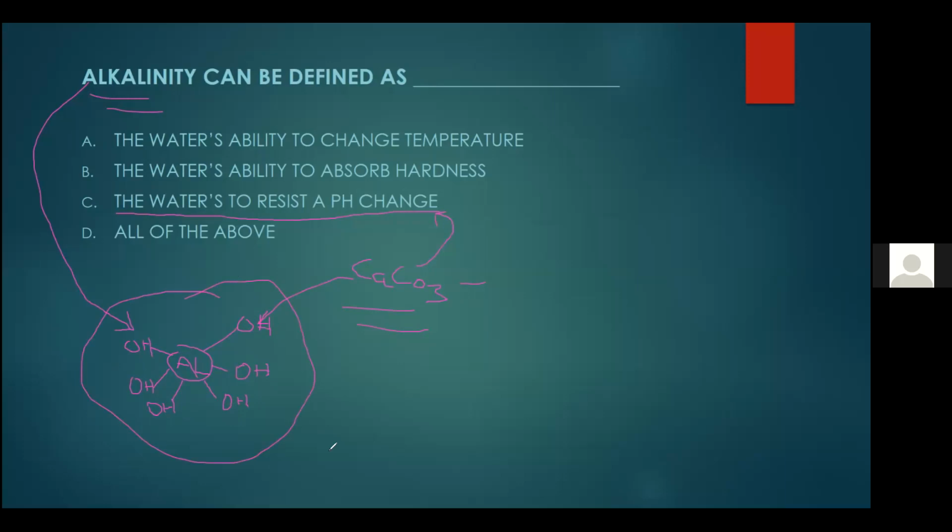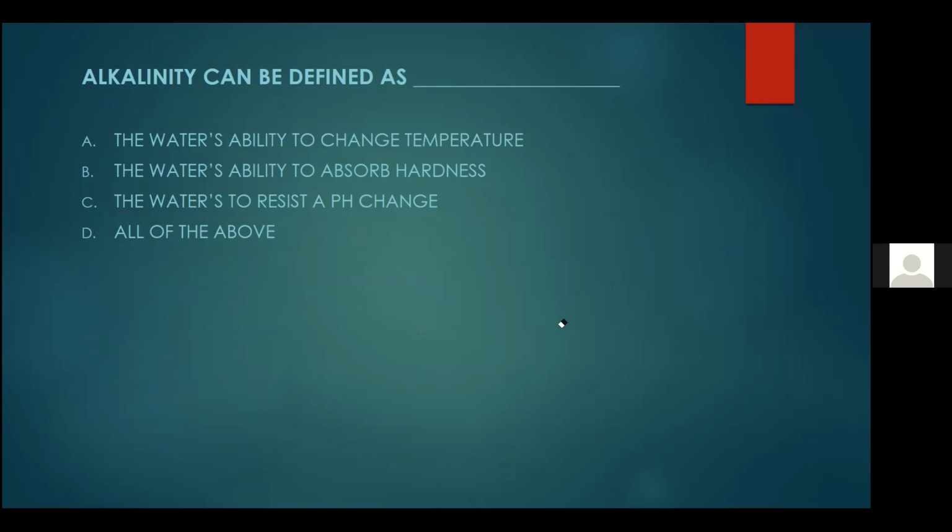So if it's not there, and for some reason, say I didn't get this arm filled, this isn't going to work. You have to have all 6 filled. So if I don't have enough calcium carbonate to fill all the arms, this thing's not going to work. So super important that we have enough calcium carbonate or enough alkalinity to make the coagulation reaction work. And it protects our pipes. It's so good.